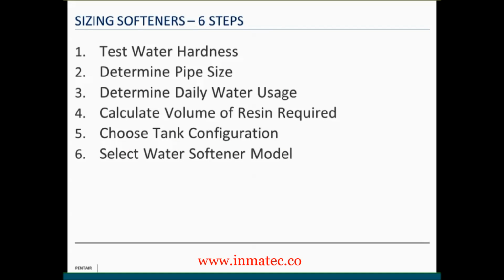And also the flow kinetics, the contact time of the water with the resin beads, is also based on that incoming plumbing water supply and the amount of water going through the softener. If you undersize the softener too much, you may go from 2-inch plumbing down to 1-inch, and that'll create a rather large restriction in your overall plumbing system. So we want to match the softener to handle the flow of the plumbing getting to it so that it passes through it smoothly and doesn't cause significant pressure drop or issues, and then it's able to actually perform its function as a water softener.